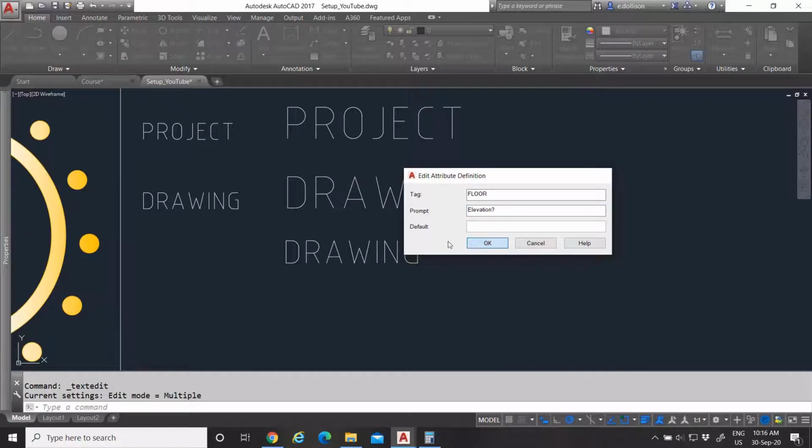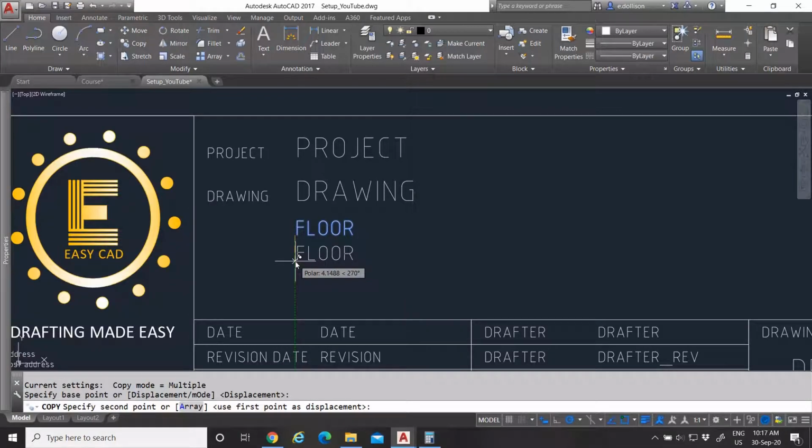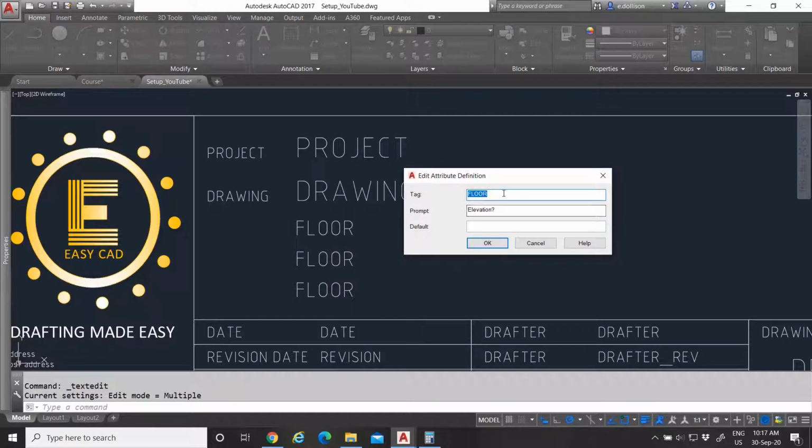And default won't be anything. And let's copy paste this right here. Let's bring it down 5 millimeters and 10 millimeters. Let's say this one will be, yeah, could be an example, room number. Let's say if you're drawing a room, and it will prompt room number.